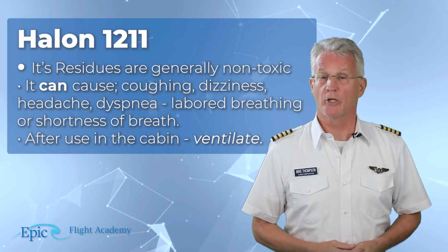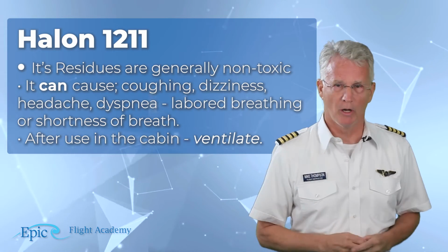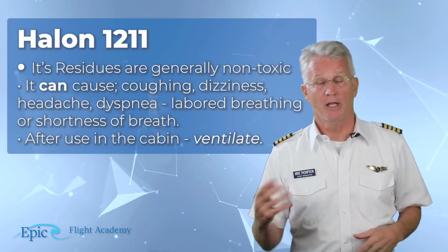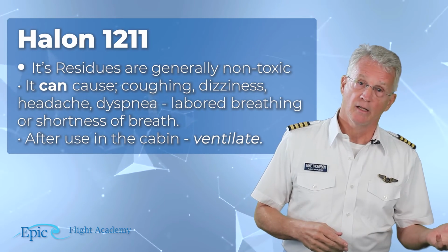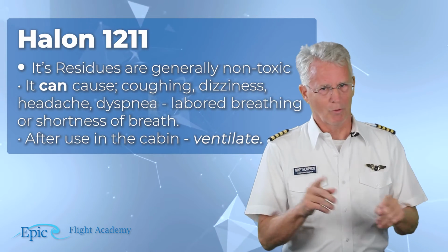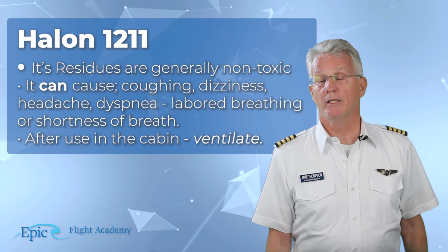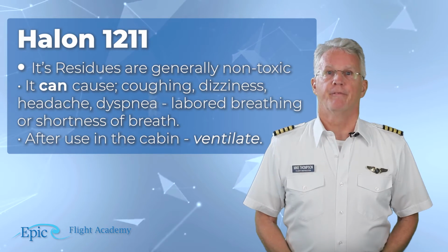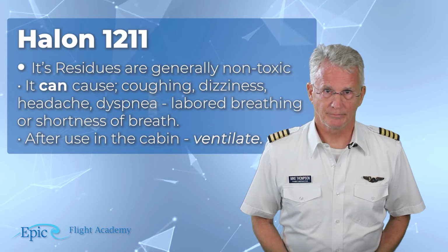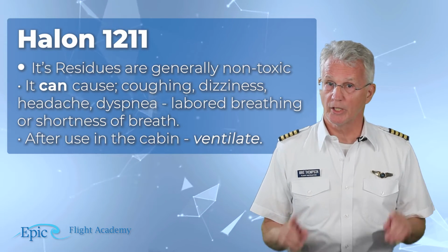Its residues are generally non-toxic. However, it can cause coughing, dizziness, headache, dyspnea. That's labored breathing or shortness of breath. So after we use it in the cabin, ventilate. Now let's have a look at our cabin fire emergency checklist.